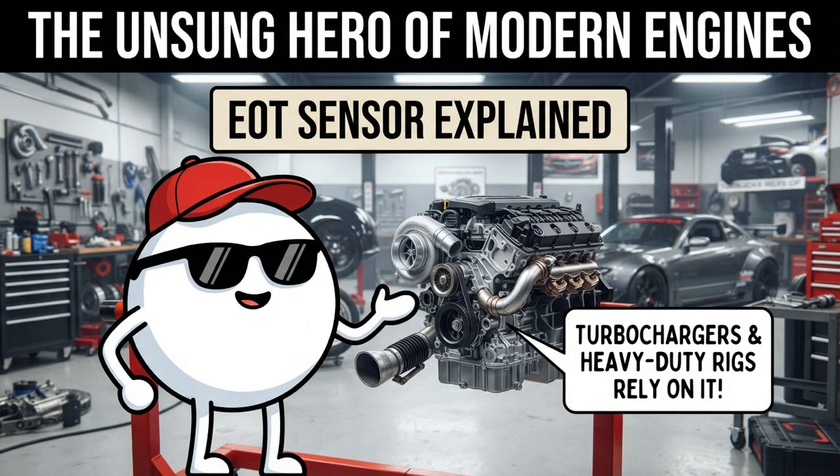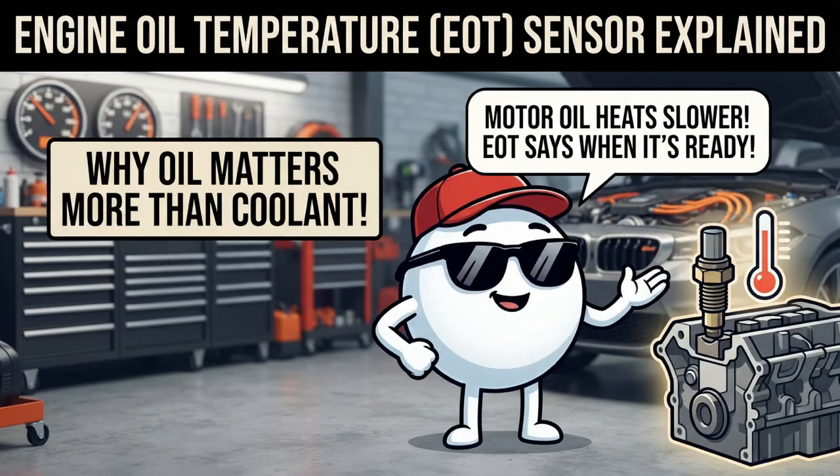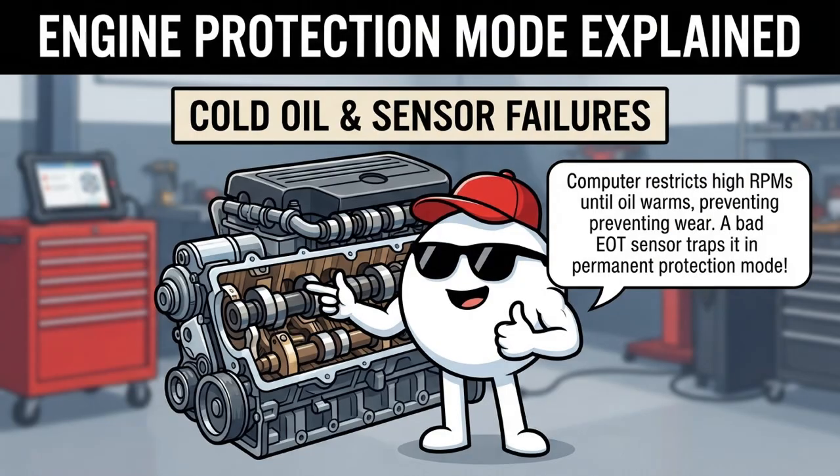Modern performance, turbocharged, and heavy-duty utility engines also rely on the engine oil temperature sensor, or EOT. Because motor oil heats up significantly slower than engine coolant, the EOT sensor informs the ECU when the oil has reached its ideal operating temperature and viscosity. Until the oil is properly warmed, the computer restricts high RPM rev limits and disables variable valve timing mechanisms to prevent metal-on-metal wear on delicate camshaft lobes and engine bearings. A failing EOT sensor can leave an engine feeling lethargic, trapping it in a permanent protection mode.